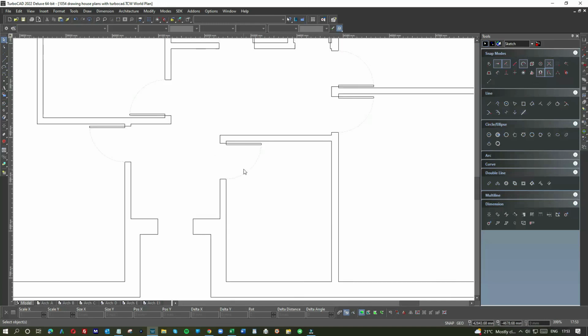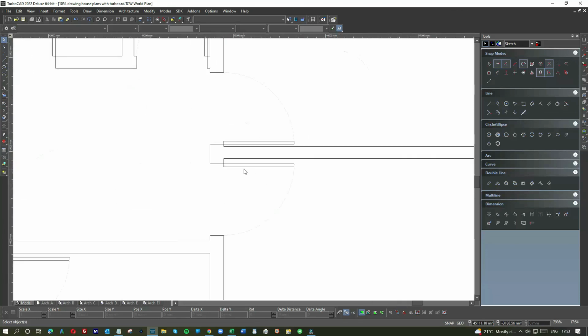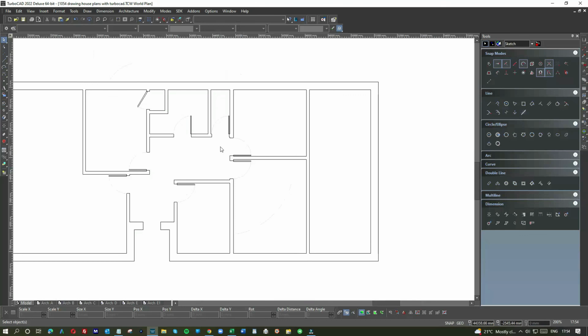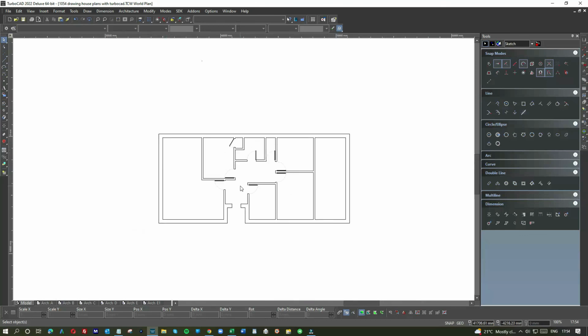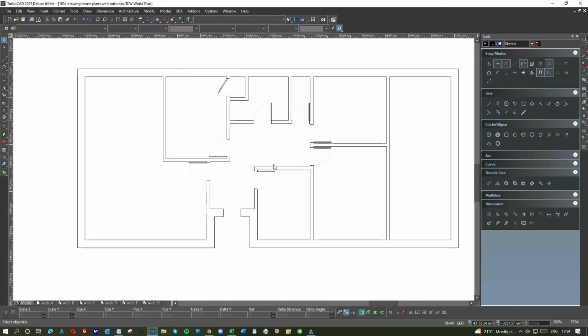So what I'm doing is I'm saying 130 for the internal walls, which is 100 block with plasterboard on either side, which is 12.5 mil, and then allow a few mil for skimming. Doors are standard 762. What more can I tell you? Nothing. You've done a great job if you've stayed with me for this one.